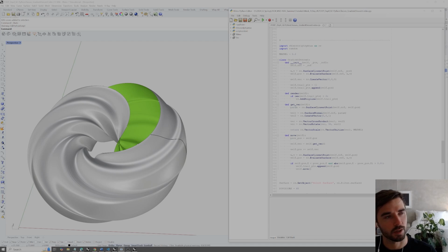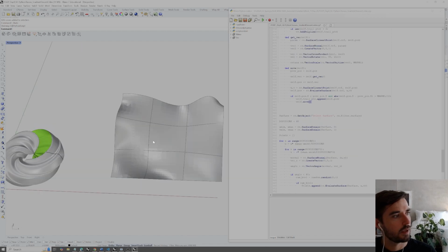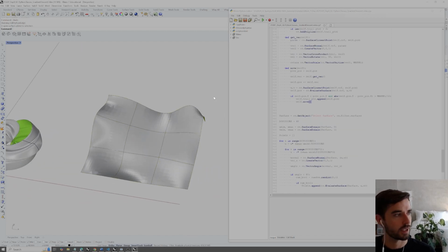So 0.01, we might want this value just divided by 10, let's say, so 0.02. Because as we decrease our max vel, the likelihood of this tolerance being met basically decreases. So we want this as a factor of max vel, and we can just call this max vel divided by 10. And if we wanted to adjust that to run it quicker, then we could do so as well. So I'll make that a factor of our max vel.